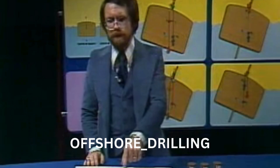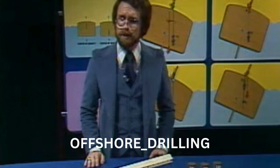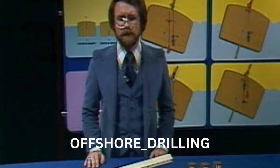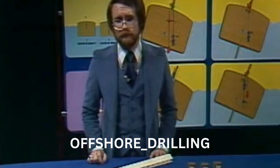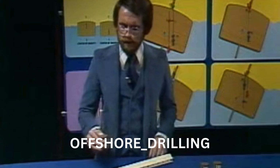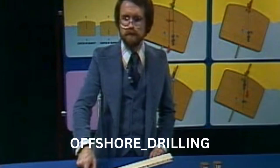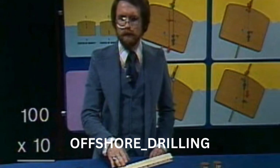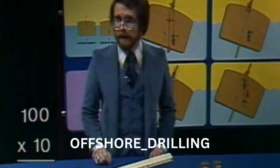We'll use G to indicate the fulcrum or balance point of the seesaw. In this example, we'll use 1 pound weights to represent 100 pounds, and 1 inch along the seesaw will represent 1 foot. So we'll place a 100-pound weight on the left side of the seesaw at about 10 feet from the fulcrum. The moments of this weight about the fulcrum are 100 pounds times 10 feet, or 1,000 foot-pounds.